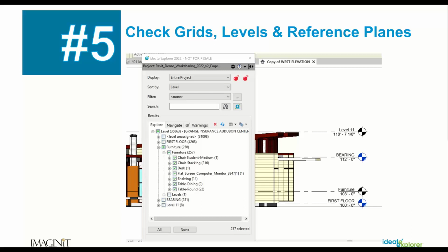How would this help for electrical? Well, anything that I'm doing here relates to anything MEP, structural, as well. So think about the things that you want to grab, you need to investigate, you need to look at when it comes to anything in your model that may be duplicates. I'm going to get into some more high-end ones for duplicating, but that query one that I just showed you, you can find out who's doing what. In-place families, people create those a lot in the MEP world. We want to investigate those for sure.